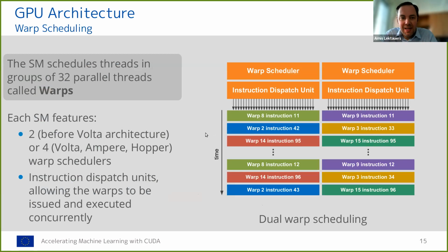Previously, I mentioned also the scheduler. So every thread that is executed by CUDA software is technically executed on the hardware side by one CUDA core at any time point. To speed up the execution of threads, there exists hardware support in the streaming multiprocessor for scheduling of thread execution. And as I said, the newer CUDA architectures implement 4 warp schedulers in one streaming multiprocessor.